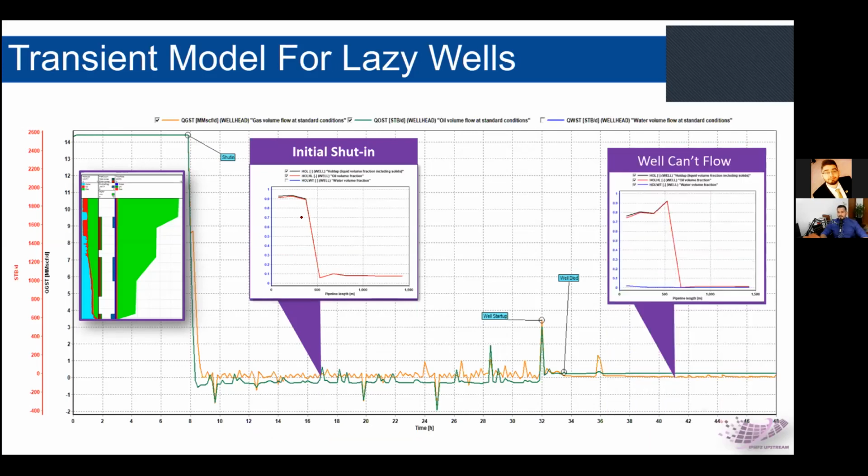What happened is that the well did not flow. We have this spike, or this initial production, came. However, the well died in half an hour or so. This is because the gas escaped so fast that it did not leave a chance for the oil to leave as well. So we need to come up with a different strategy to tackle this problem.